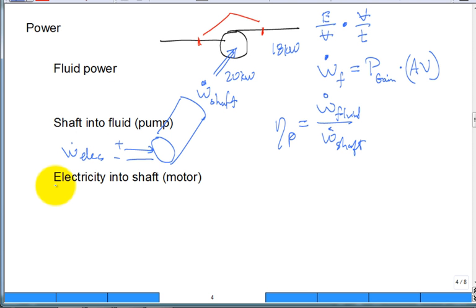Very simply, if it's a single phase and you have no phase lag or anything, then it's just the RMS voltage times the RMS current. But if you do have 3-phase, you have square root of 3 over 2, and then if you have a power factor, a lag between the voltage and the current, you have a power factor term in that power calculation. So it's a little bit of work, but in principle, it's just the electric power. And CPS is selling electric power. You're going to have to pay for that.